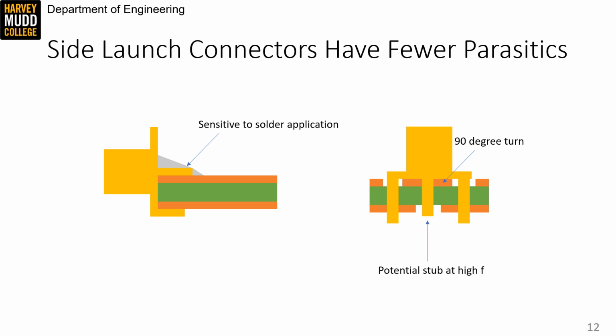So connectors come in larger and smaller sizes, just like components. And small connectors like UFL are popular for some of the same reasons that small components are popular. However, SMA connectors are really the workhorse for lots of mid-gigahertz design and prototypes. Designers tend to switch to UFL for very compact designs, like antenna mounts for cell phones and stuff like that, and to 3.5mm connectors for very high frequency designs.